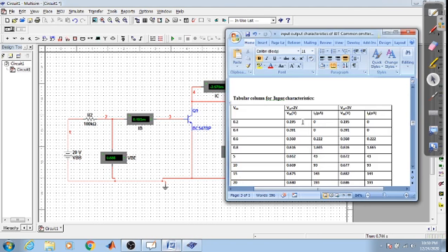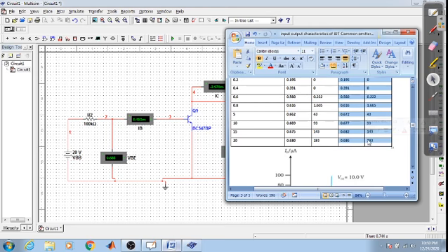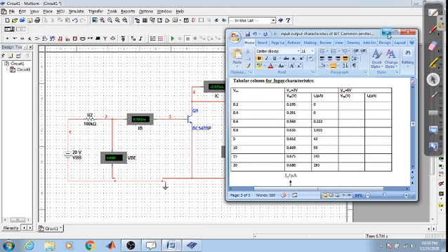This is almost resembling what we had for VC equal to 2 volts. Whatever the voltage you have set, the same readings you are getting here also. So you do one thing. Instead of VC equal to 3 volts, you make VC equal to 6 volts and repeat the readings again. So for example here, let us clear this. So for VC equal to 6 volts.